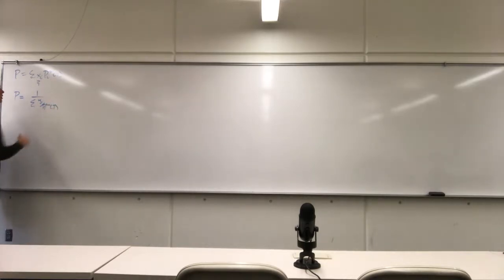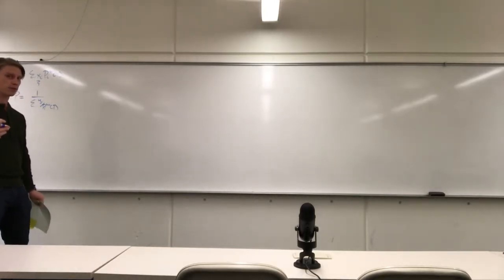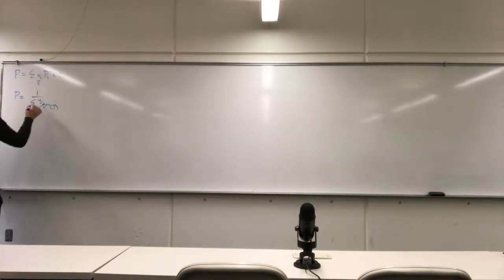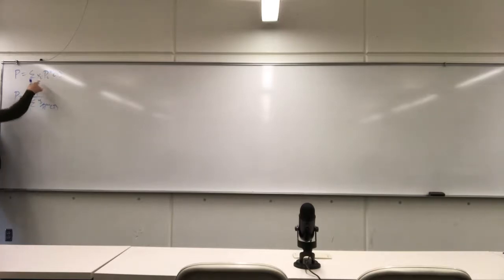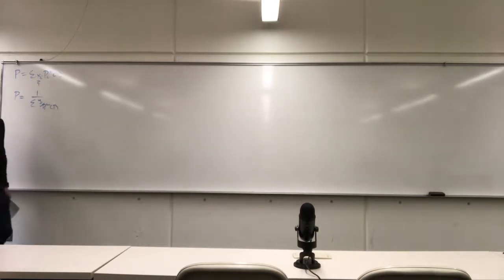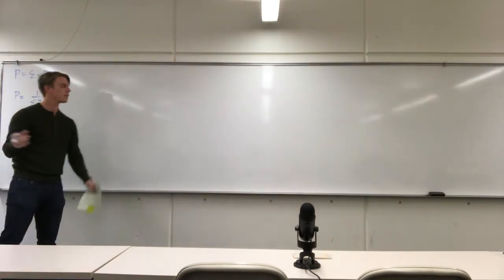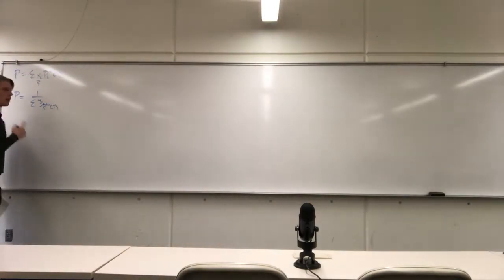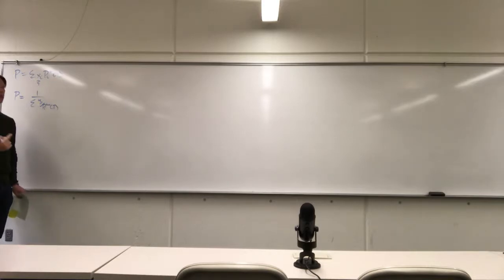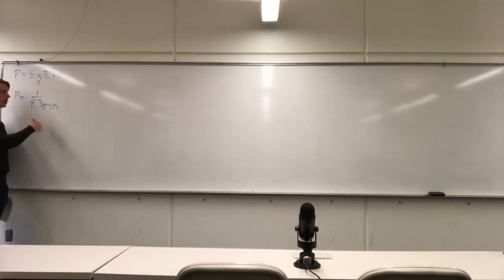Remember, these equations are good for all circumstances of vapor-liquid equilibrium. The only thing that makes them powerful for the bubble and the dew is the assumption of whether or not we know what the liquid composition is or whether we know what the vapor composition is. Since you're creating the curve, you have ultimate authority to do whatever you like, right? So, in the bubble curve, this is an explicit equation. I have a temperature, I have Antoine's equation, I can get the vapor pressure, I know what my composition is, boom, I get my pressure.